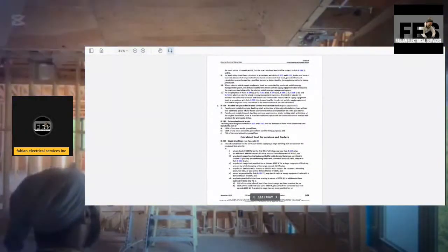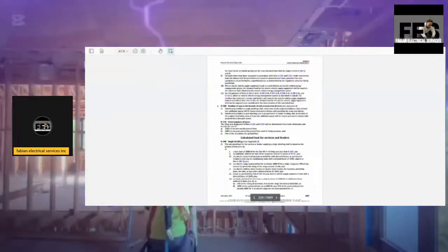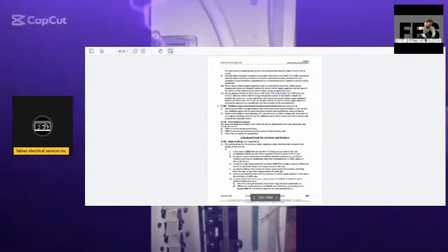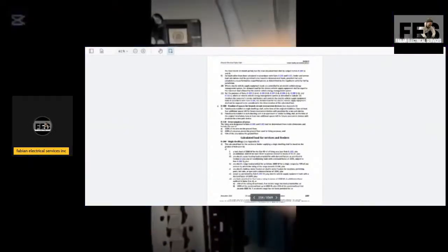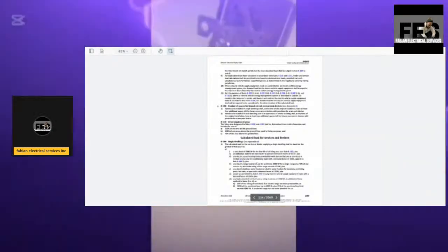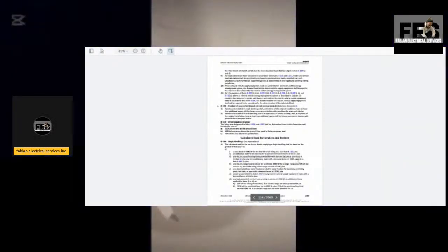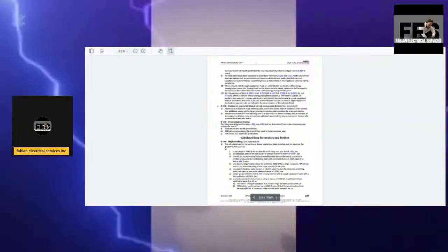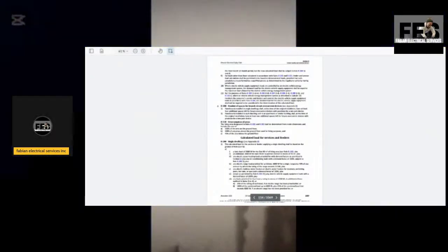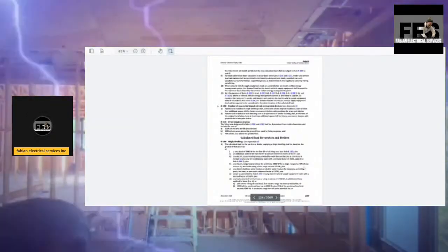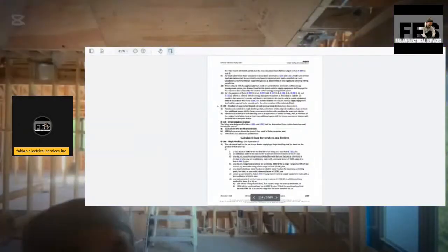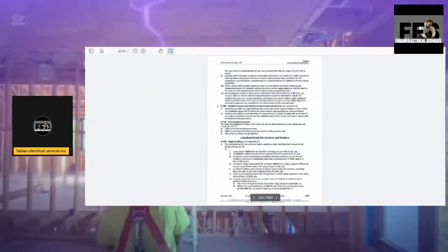Plus an additional 1,000 watts for each 90 square meters or portion thereof in excess of 90 square meters, plus any electric space heating loads provided for with demand factors as permitted in section 62, plus any air conditioner loads with a demand factor of 100% subject to Rule 8-106, plus any electric range load provided for as follows: 6,000 watts for a single range plus 40% of any amount by which the rating of the range exceeds 12 kilowatts.